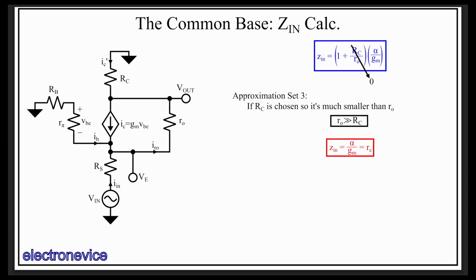As we discussed at the beginning, the input impedance is quite small. Even with a fairly small collector current of 100 microamps, Re is still about 260 ohms. At 10 milliamps, it's only 2.6 ohms. So it's a pretty small value over most reasonable collector current ranges, especially the higher ranges. So not an ideal input impedance for a voltage amplifier.